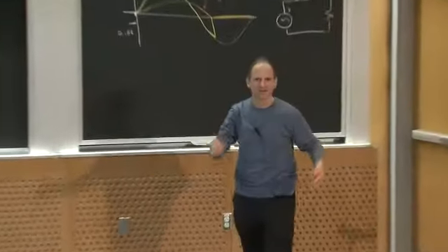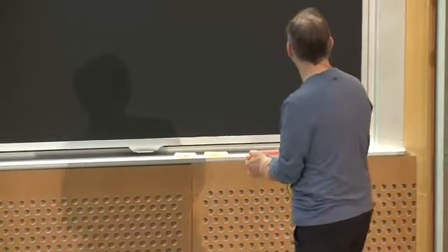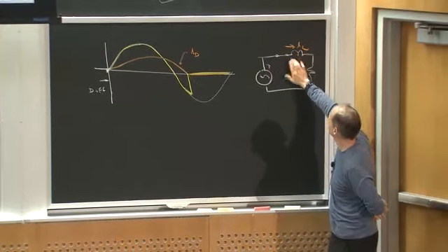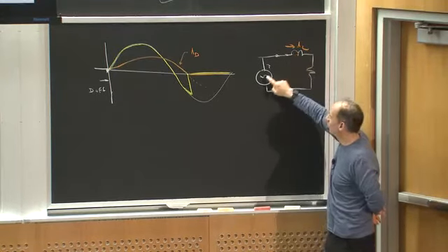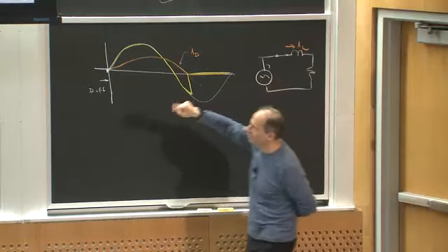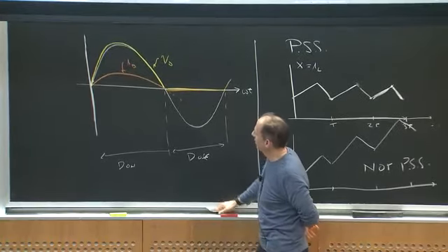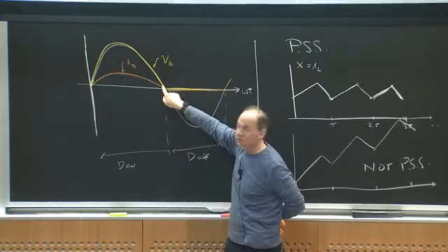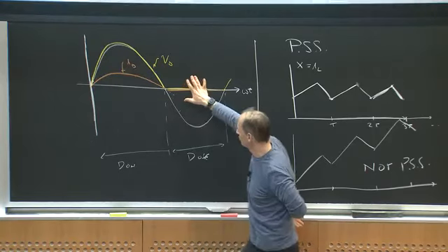So what would I do to fix this, right? The real problem I have is what's going on here. This voltage went positive, diode turns on, I start shoving current through the inductor, okay? Voltage goes negative. What I wanted to do, and what happened over here, okay, was that when the voltage went negative, the diode shut off, and then I got 0, which is what I wanted. So I had the positive part of the sine wave, and then 0 for the other half, and I got